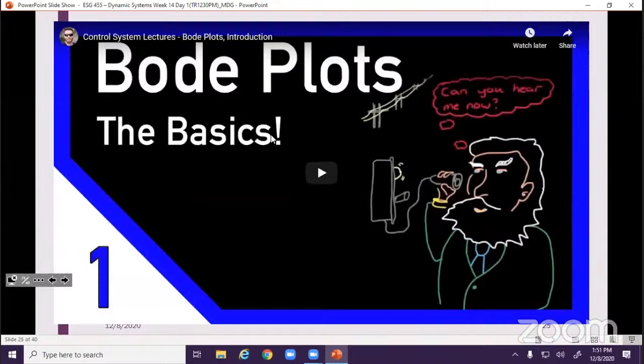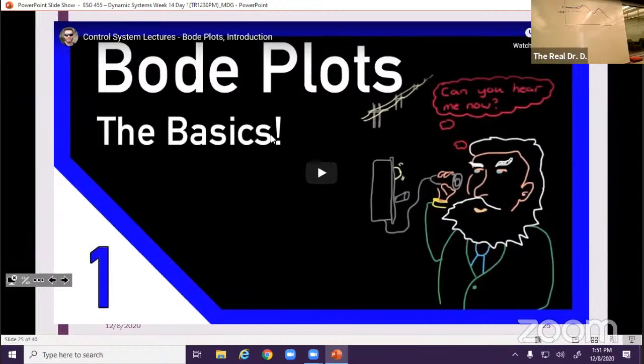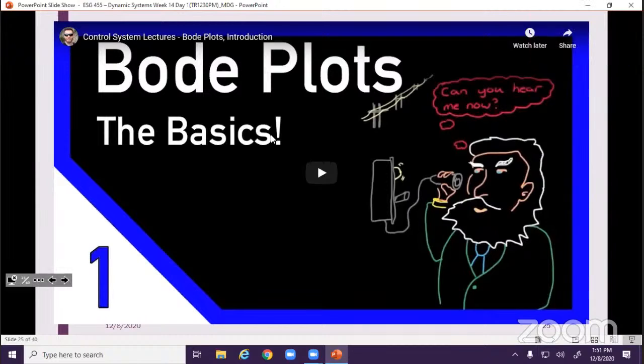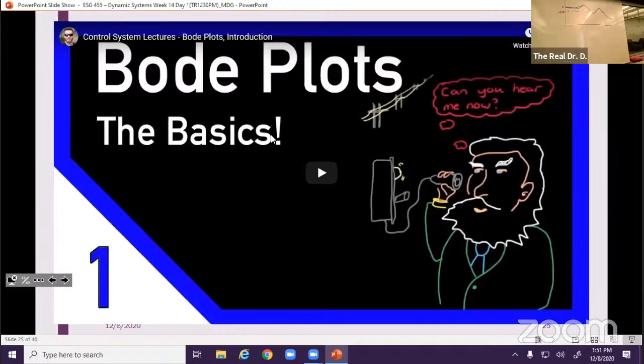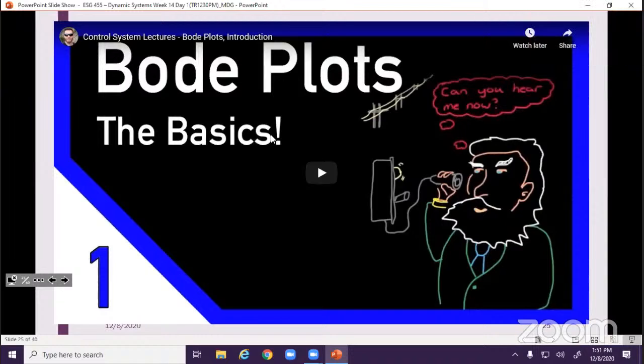For a Bode diagram, if you're using Simulink, is there a Bode command, like a scope? Is there a Bode equivalent? No, it's a mess in Simulink. Just use MATLAB. Oh, okay, good to know. The thing is, Trevor, there's no need to do a Bode diagram in real time, because the Bode diagram of the transfer function is never going to change. Oh, that's true. Okay.